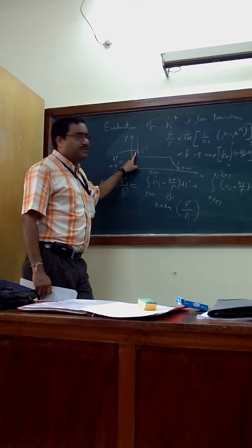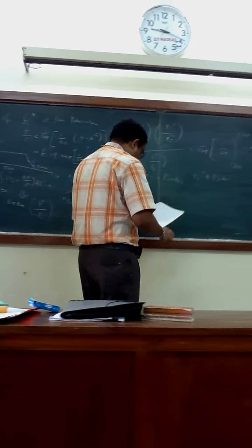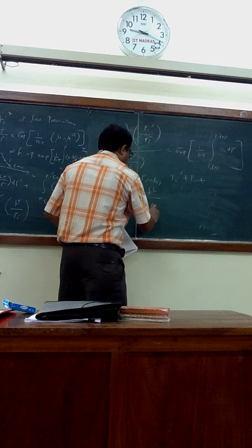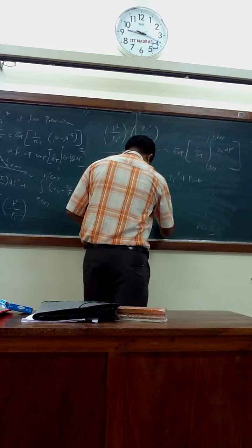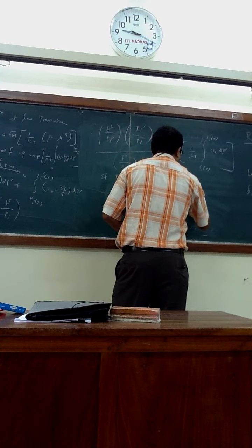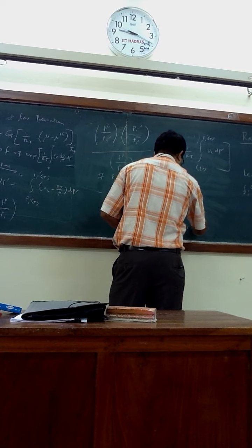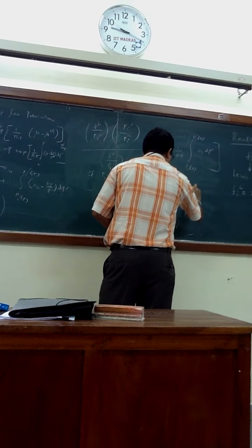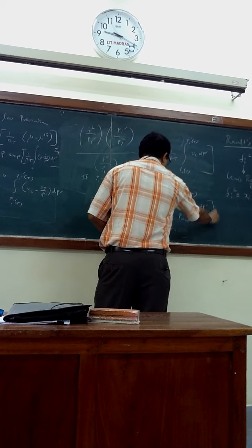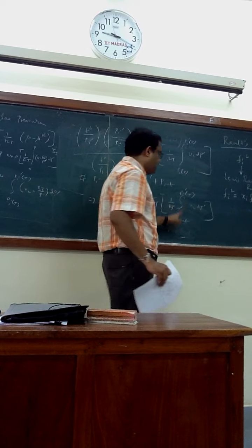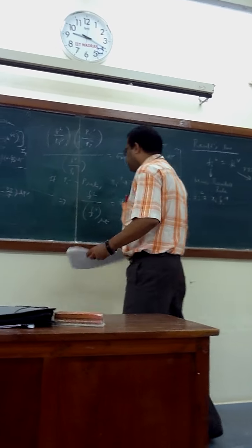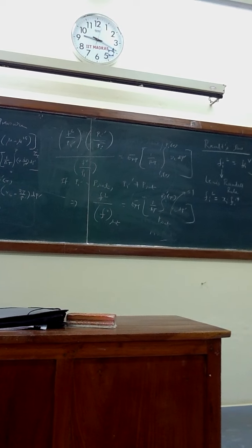So FL by FB sat equals exponential of 1 by RT, integral from Psat to Pi prime of VL dP prime. At very low pressure, this difference is very small, so this goes to 1. So FL equals FB sat.